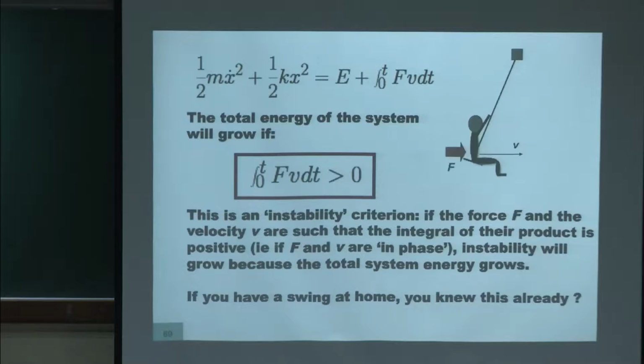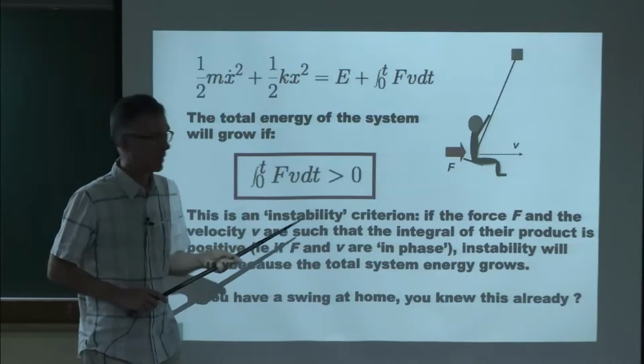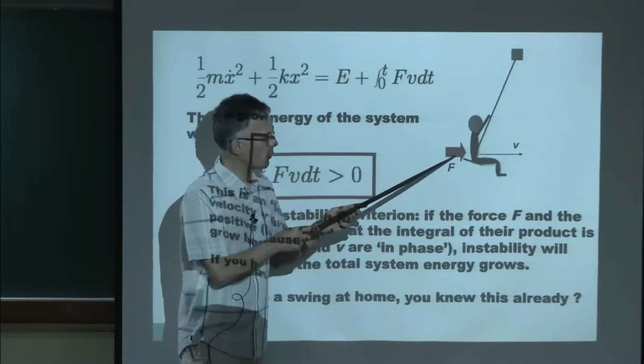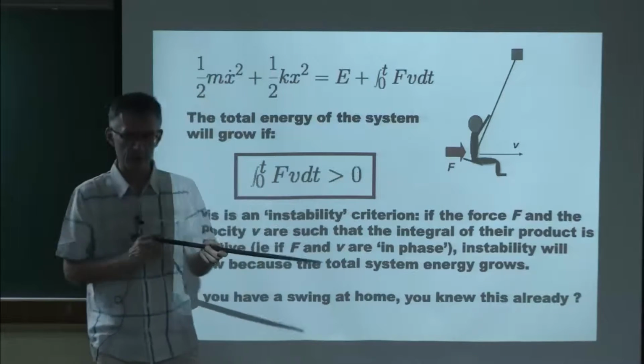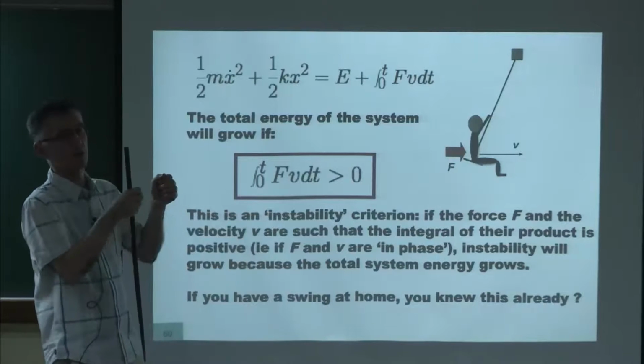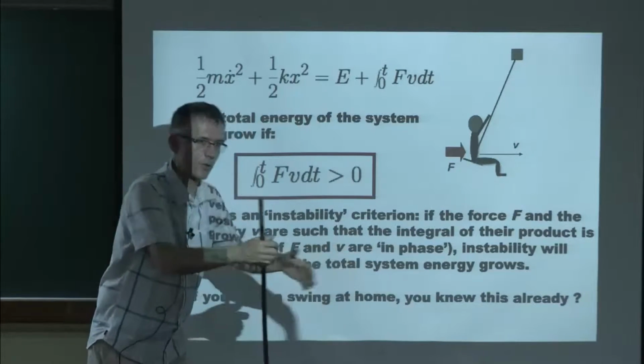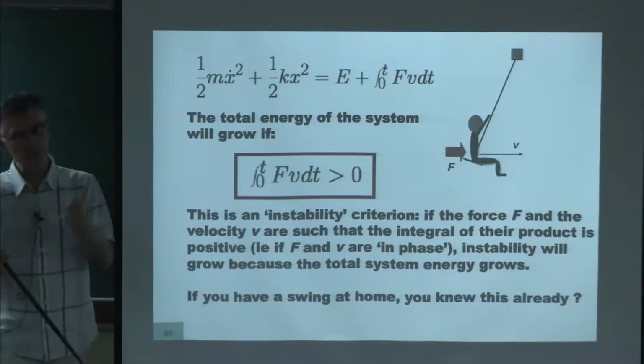So this is here a very intuitive test. If you have a swing at home and you push your little sister, you know that you have to push when the velocity is positive. If you push when the swing is coming towards you, you damp the instability. If you push when the swing is going away from you, you excite it. It's going to be the same in combustion.